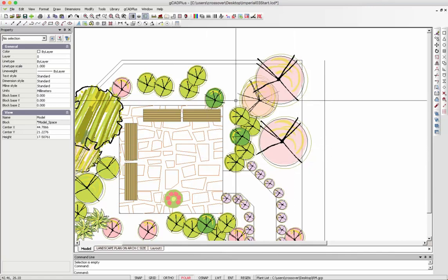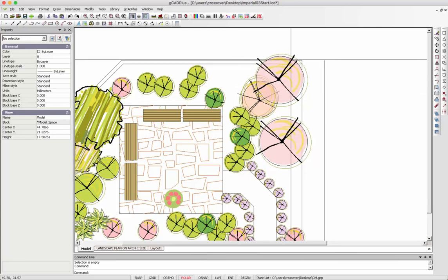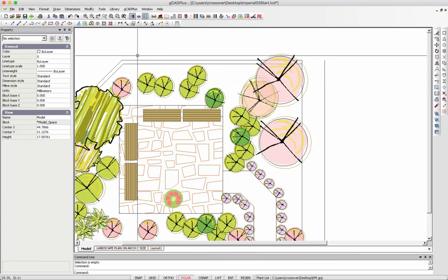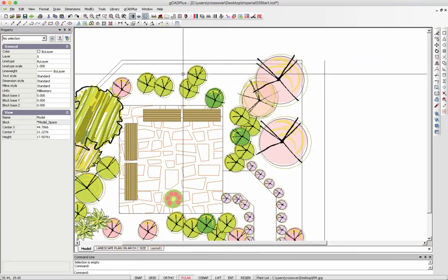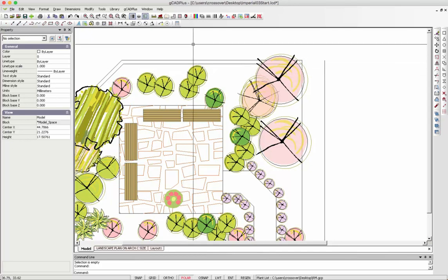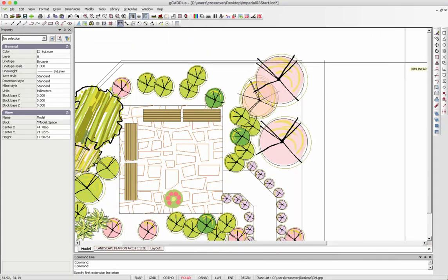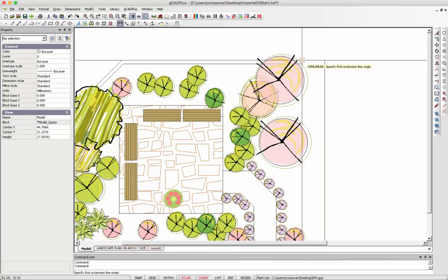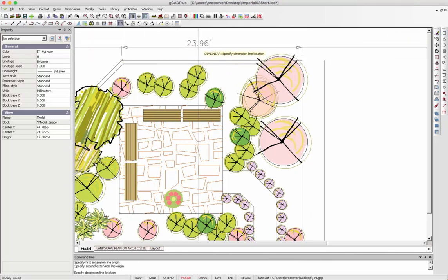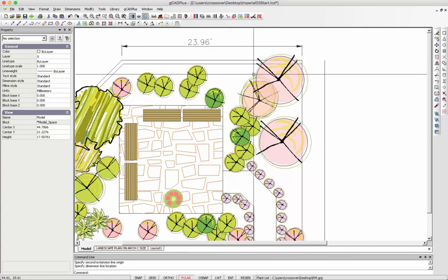So to apply a dimension to, say, the wall through here, you apply an external or an internal dimension. Let's do it externally for the moment. We'll pick this tool here, linear dimensions, and this time you want some precision, so we will dimension from that endpoint there to another endpoint here, and I'll just move my line up.